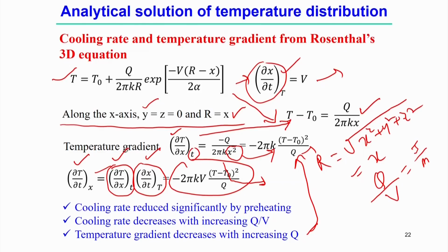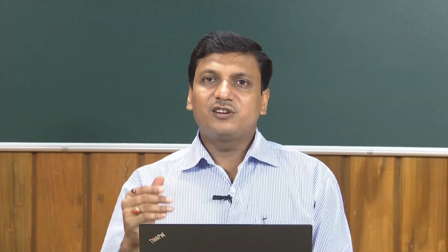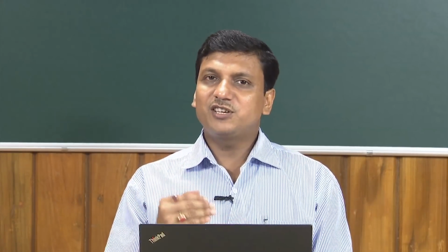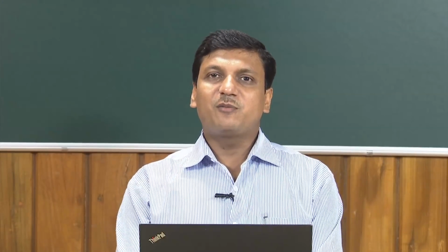This kind of conclusion can be drawn simply by estimating the cooling rate from the analytical solution of the temperature distribution, and that analogy can be linked with the actual process condition. When we do a welding process physically, we can analyze these parameters to see whether we can increase or decrease the rate of cooling, because the cooling rate is a very significant parameter in the solidification process, and the final microstructure is influenced, or maybe decided, by the rate of cooling. So, the cooling rate is a very important parameter for analyzing the welding process.